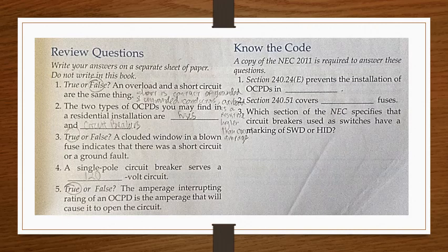Know the code? Question 1. Section 240.24 E prevents the installation of OCPDs in blank fill-in, that is bathrooms, according to the 2011 NEC, page 70-95. And again, I recommend that you read chapters 1 and 2, at least for now, of the NEC. Chapters 1 and 2 are a wealth of information when it comes to understanding the NEC. So read chapters 1 and 2 from beginning to end.